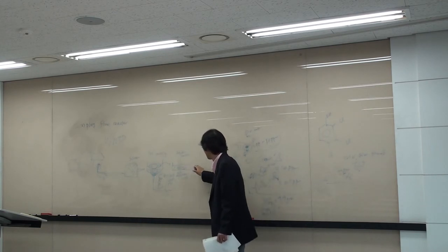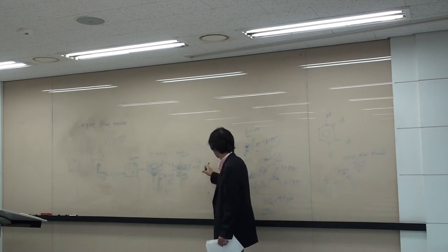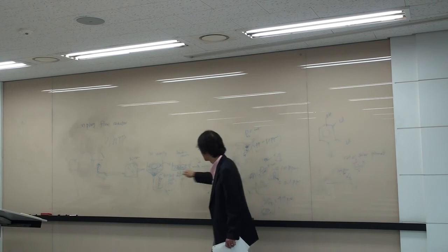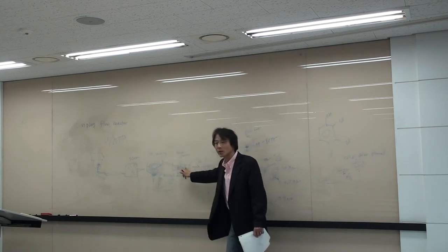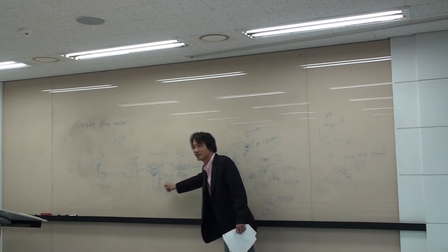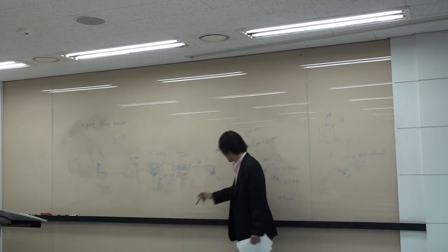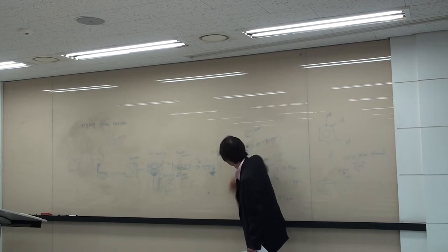And this is the bioreactor, and then this is mixed liquor overall. Then it goes into the secondary settling, where sludge is collected and clean water comes out. So compared to this one and this one, what's the difference? The microorganisms eat up all the carbon, nitrogen, and phosphorus. The concentration of carbon, nitrogen, and phosphorus is very low, right? So now it is time to discharge.